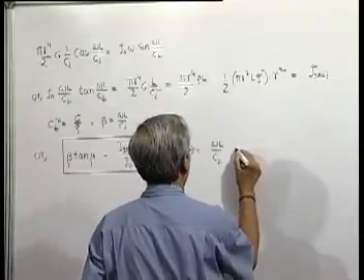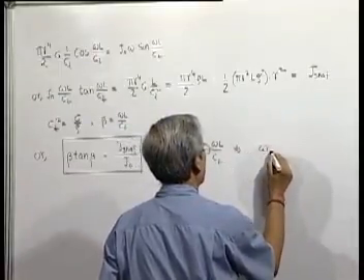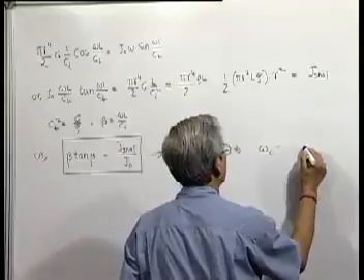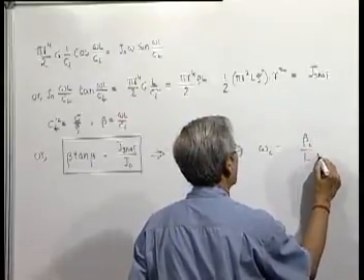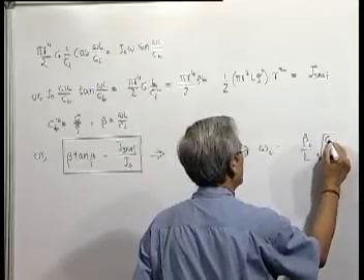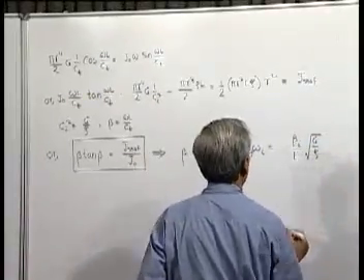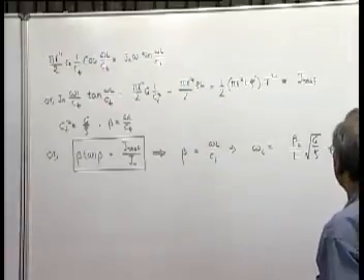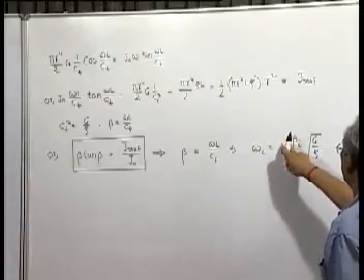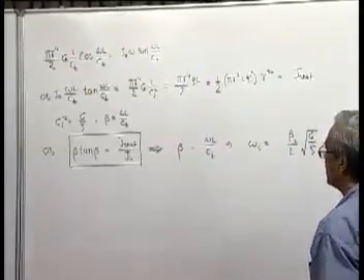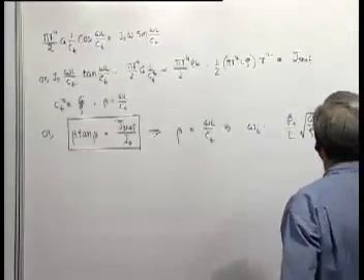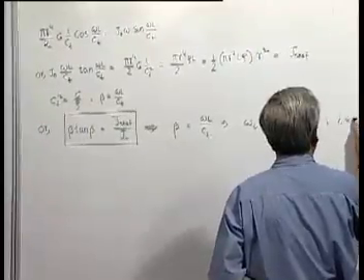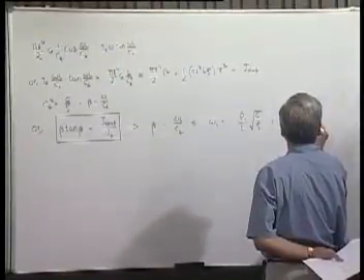So from this we will get a particular value of omega i, which is nothing but beta i by L into square root of G by rho. So substituting the value of beta here, what we get from the transcendental equation will give us the corresponding frequency, and of course i will be 1, 2, 3.